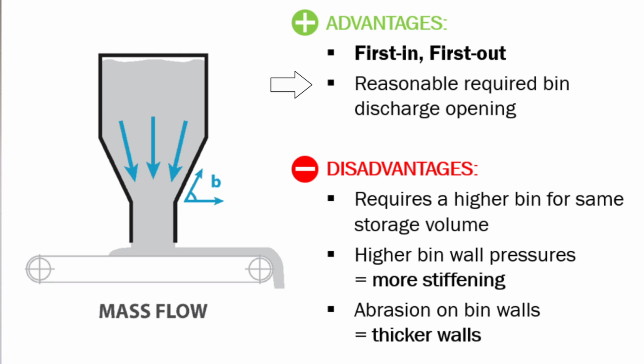The second advantage, and this one is really significant and maybe a little bit underappreciated, is that the geometry required for reliable discharge can be more reasonable. Specifically, the minimum discharge opening is often much more workable than if you were designing for funnel flow.